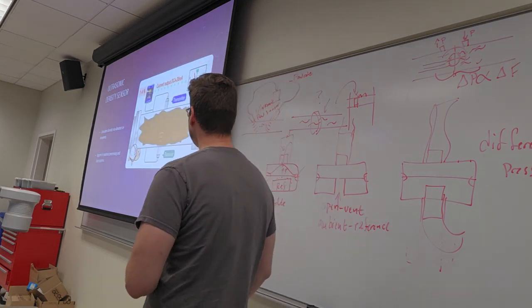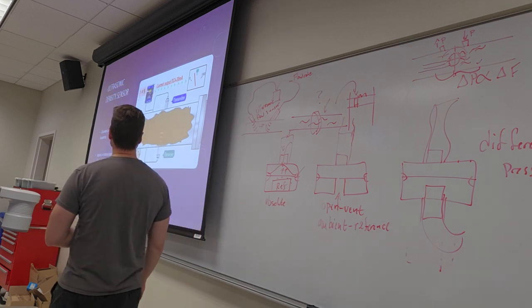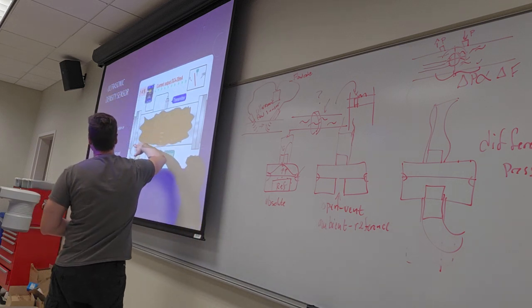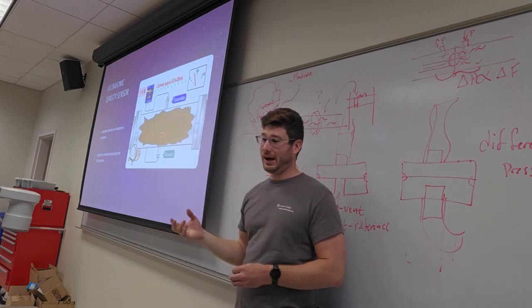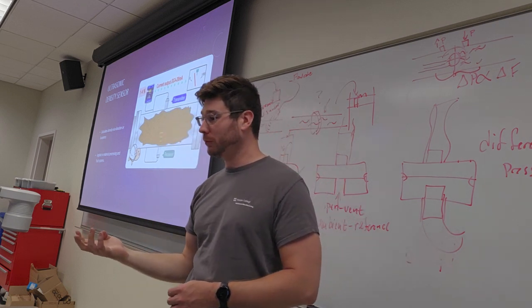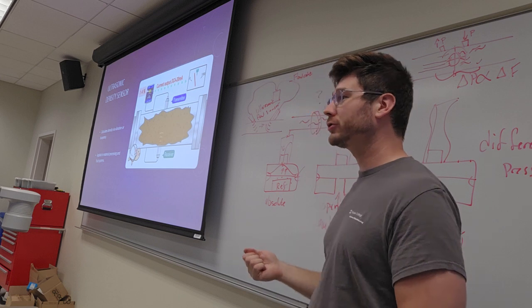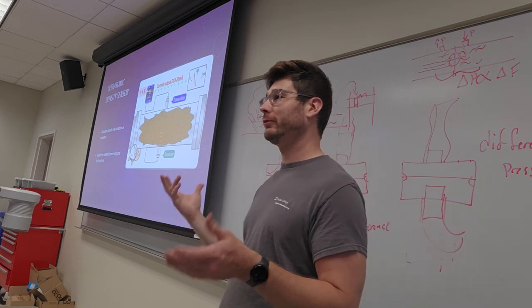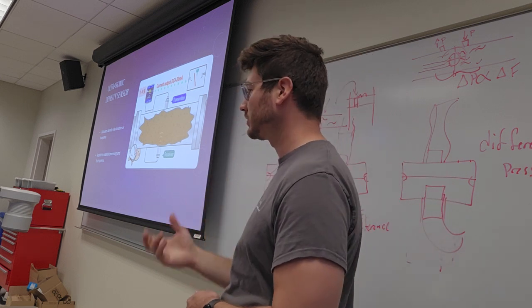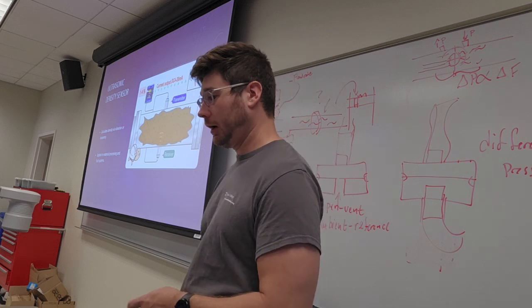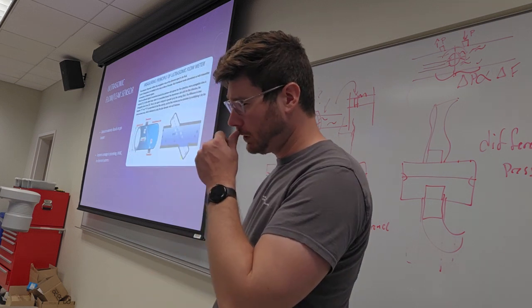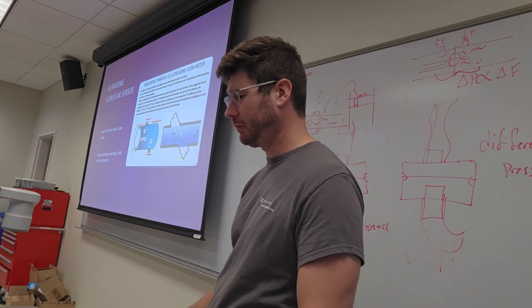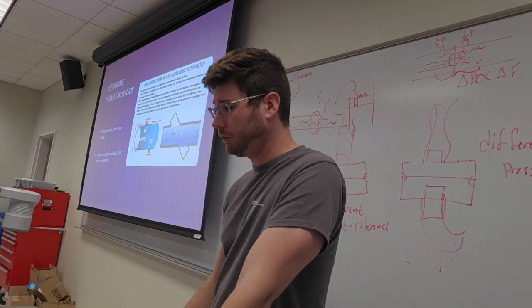Oh, nice. So here is that example that I was talking about, instead of a flow sensor, this is a density sensor. So we have sludge through a pipe, right? And essentially how much ultrasound is absorbed or reflected by that sludge would vary with density, it would vary with flow rate. And we would have a specific sensor that would report that data to us. Okay. Also used a lot in leak sensing for very, very small amounts of fluid flow for ultrasonic.